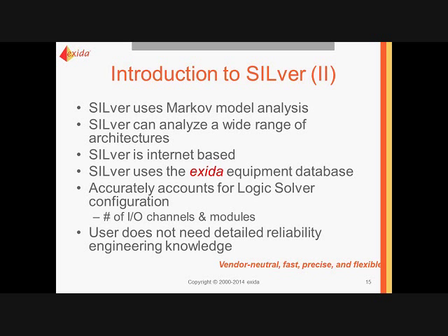Now, a lot of people still do PFD average calculations or PFH calculations using spreadsheets, which is fine if you're doing it for a simple architecture, a single architecture, in fact. But you still have to have reliable failure rate data, and that involves being able to get hold of the manufacturer's failure data reliably.